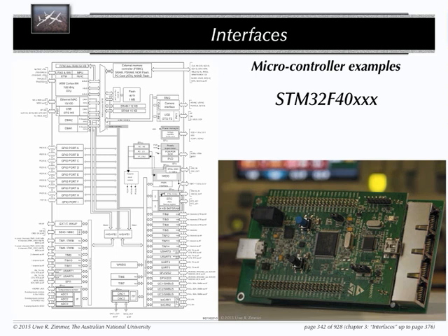What else you have on this device? I mean, it's not proportional to the space here. Of course, the GPIO ports are not that large compared to the rest of the whole thing. But you have a lot of other interesting devices on that thing. We have 3 independent 12-bit ADCs on that one, and the temperature sensor is cleverly integrated into that block. It makes a lot of sense because you calibrate your ADCs and you calibrate this whole very sensitive part of your device. You want to have good temperature measurement right there, which you get straight away.